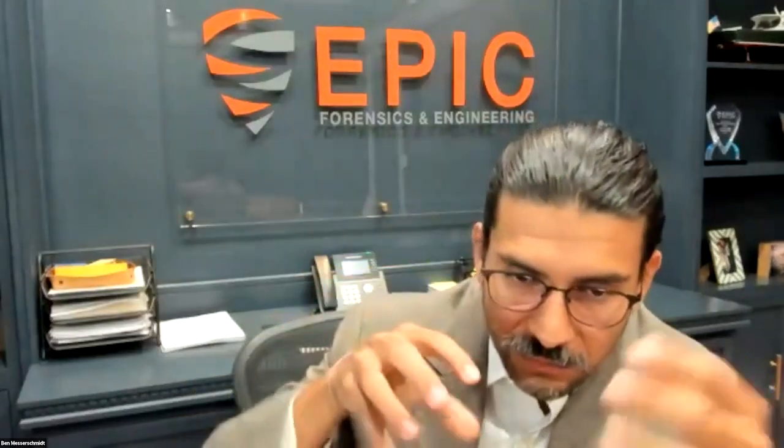Advice about hot crack filling. So this is essentially going to be the crack sealing that we were talking about. It being hot is essentially you just having a kettle on site to pour it in hot to get that to permeate further down. Again, it's going to be less viscous. It's going to be able to actually better coat the area.